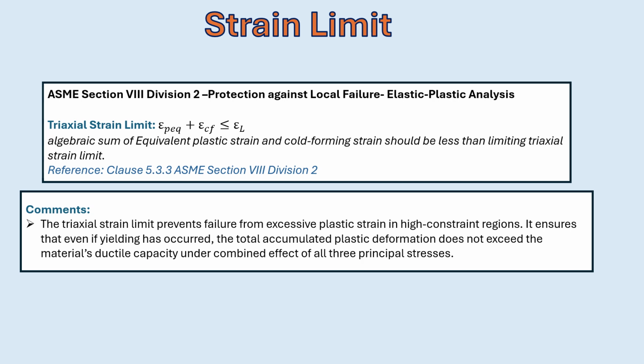The strain limit is the algebraic sum of equivalent plastic strain EPEQ and cold forming strain ECF, which should be less than the limiting triaxial strain limit, which is the EL value.